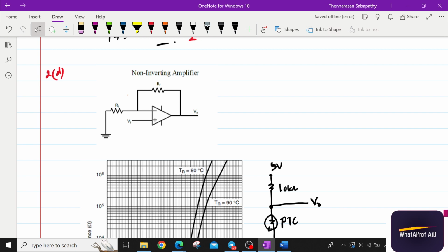Then as for the temperature, if the 10 millivolt per degree Celsius standard is replaced with the PTC thermistor, they ask what would be the V out of this one, maximum and minimum.